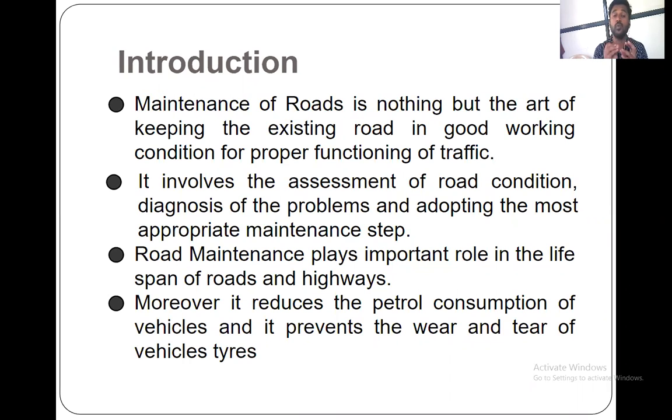Okay, so before going for the remedial measure, first we need to diagnose the problem from the root. Once we know the root cause of the problem, then we will take it out from there. Suppose a loose material remains, then after some period of time the failure of that road will occur again at that point. So we need to remove all the loose material at the pothole. Then we need to place another material and go for the compaction.